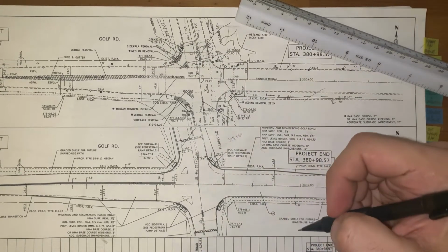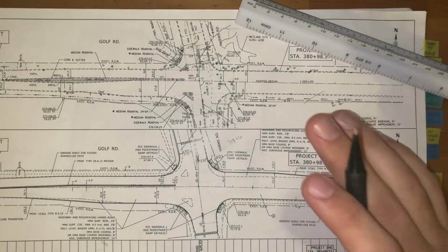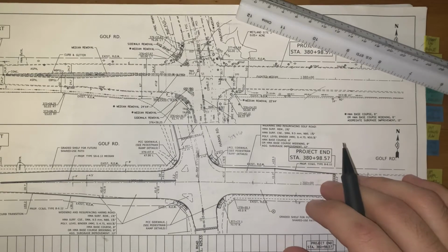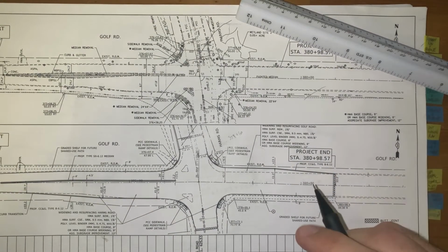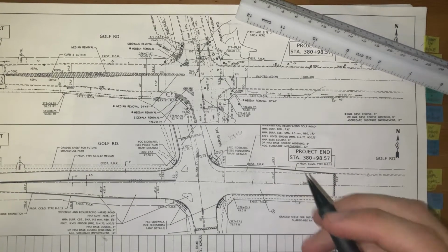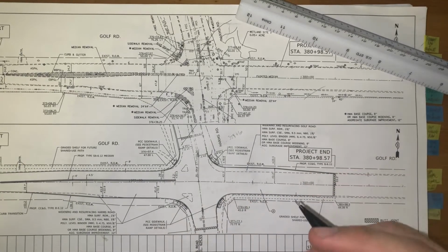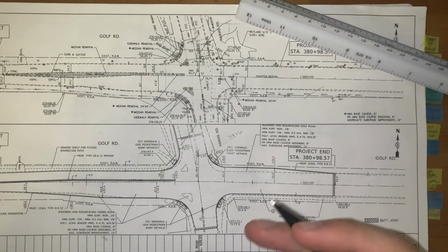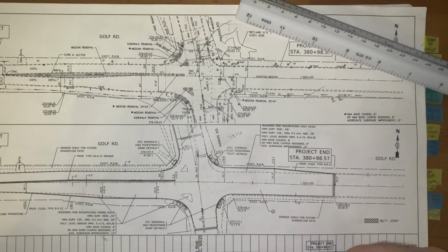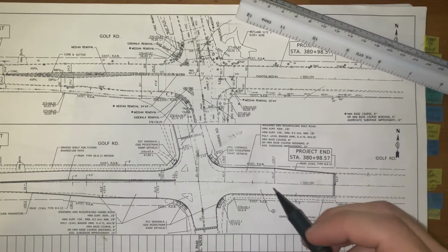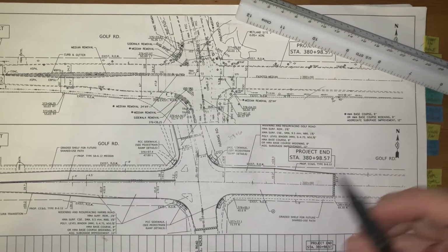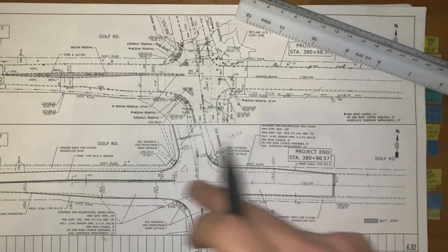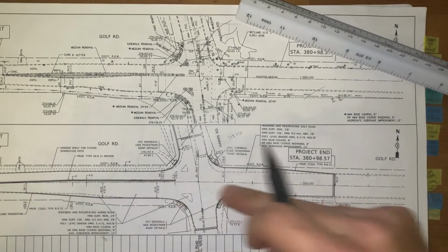Like I said, I'll be talking about stationing and offsets because it's important to also know offsets and how they play in correlation with stationing. Every item that's indicated on the plan view will have a correlated offset because you need to know in which direction it is referring to. Offsets are typically governed either in the northward direction or in the eastward direction. In this case, our street is going east and west.